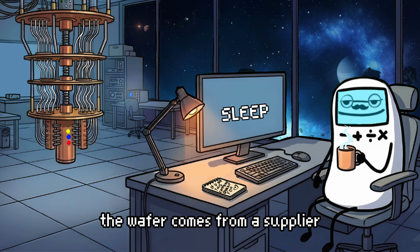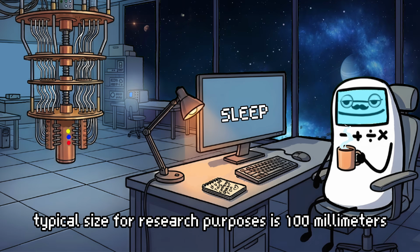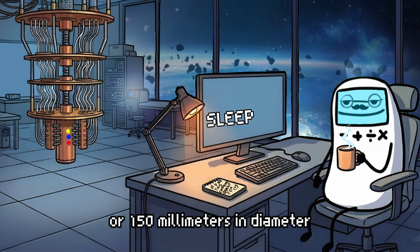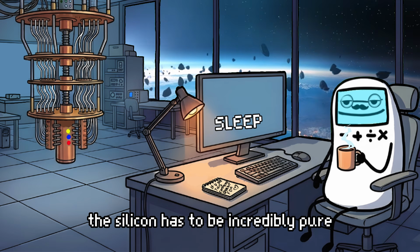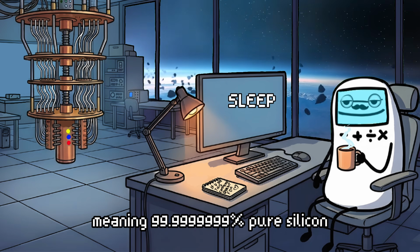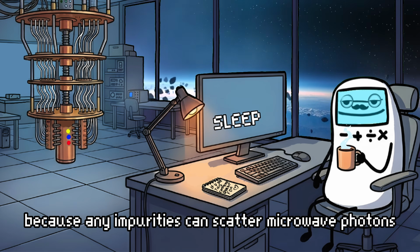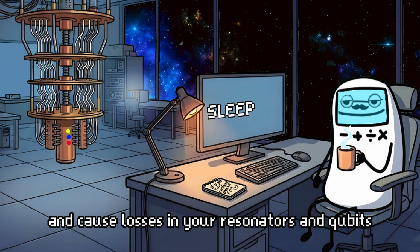The wafer comes from a supplier as a disk of highly pure single crystal silicon. Typical size for research purposes is 100 millimeters or 150 millimeters in diameter, which is 4 or 6 inches across. The silicon has to be incredibly pure, like 9 nines of purity, meaning 99.999999% pure silicon, because any impurities can scatter microwave photons and cause losses in your resonators and qubits.